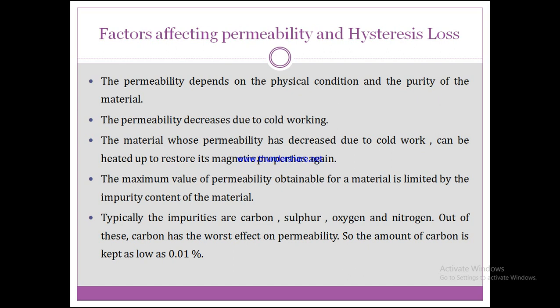Out of these, carbon has the worst effect on permeability, so the amount of carbon is kept as low as possible. That means it should be kept at 0.01% of the material. So these are some parameters which generally affect the permeability and hysteresis loss of a material.